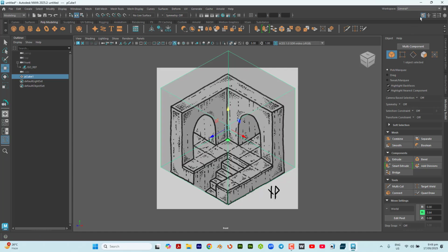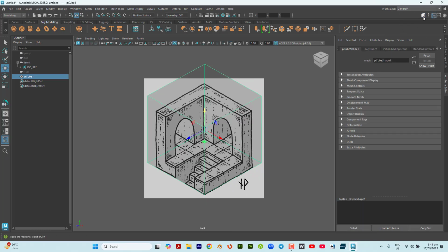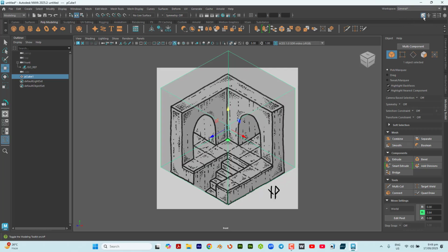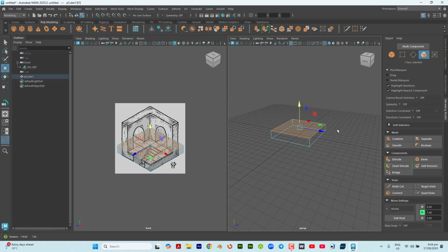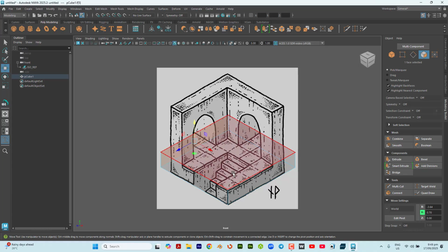Now let's switch here to the modeling toolkit. Once I have clicked the modeling toolkit, I'll select the polygon selection here, click that, and then I'll switch to the move tool, or I'll press letter Q, and then I'll push this down so that it will be leveled onto one of the blocks here, or onto the floor level. Spacebar, and then this time I'll select this, spacebar, and then I'll drag it along the x-axis, the red arrow there. Now it is fitting.